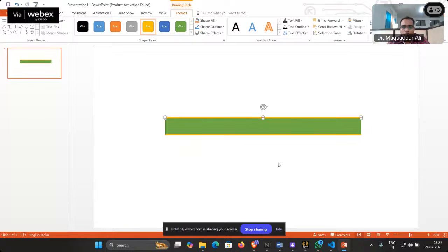This is a typical PCB sheet, the cross-section view of a PCB, in which we have a copper layer, then a substrate, and again a copper layer. When we are designing, we are basically etching some part of this upper layer to design our antenna, and sometimes we also etch on the ground layer.